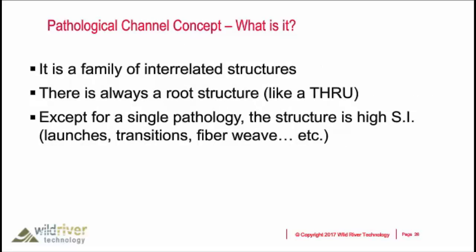They represent a family of structures, and you start off with a root structure like a through. And this whole approach lends itself to doing de-embedding, and it's also very EDA friendly. The through establishes a reference and helps you model the entire system. The importance is to be able to model the system and to be able to run it and have measurements and simulation run cohesively. In addition, comparing that to the internal tools of the SerDes. And I'll be talking about that later also.